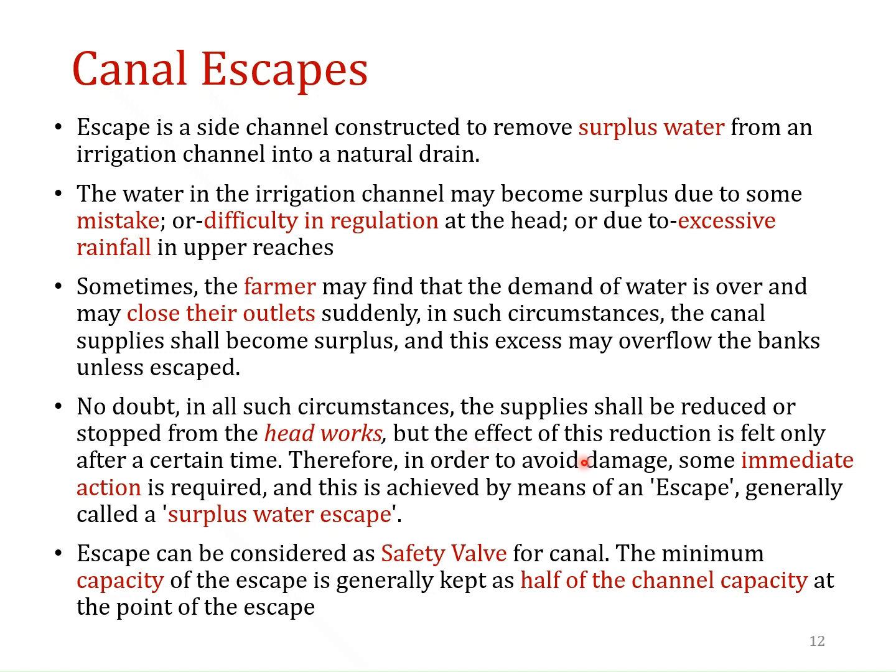But the effect of this reduction is felt only after a certain time. Therefore, in order to avoid the damage, some immediate action is required, and this is achieved by means of escape, generally called surplus water escape. Okay, so you can consider these escapes as our safety wall in the canal.